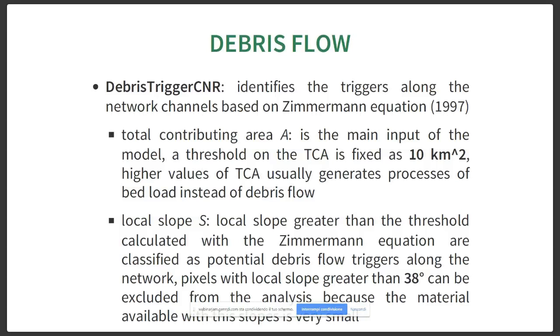Pixels with a slope greater than 38 degrees can be excluded from the analysis because usually over this gradient the material available is very little.